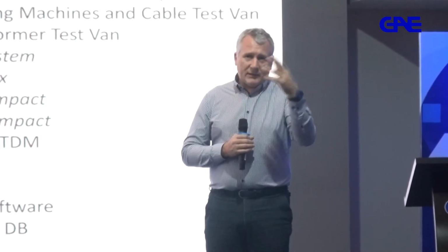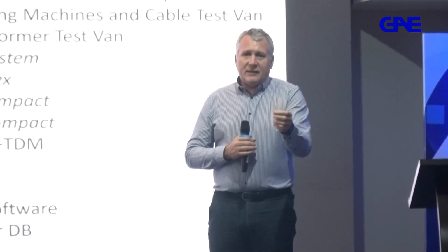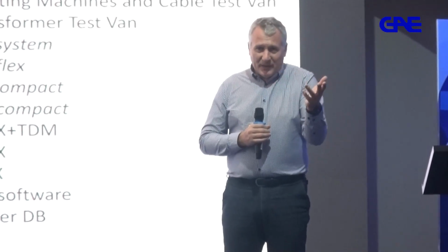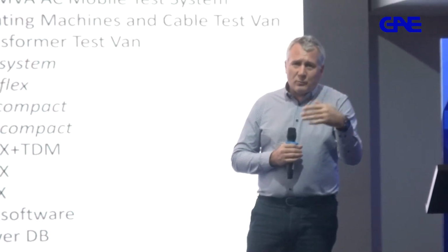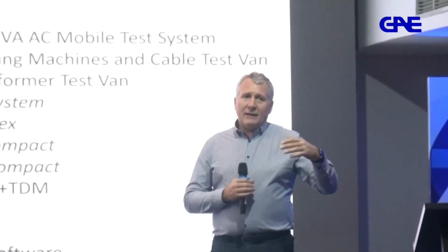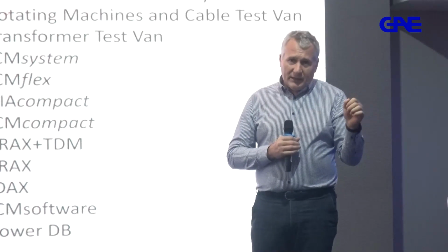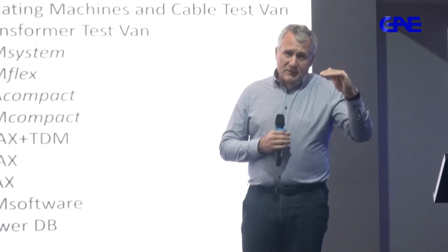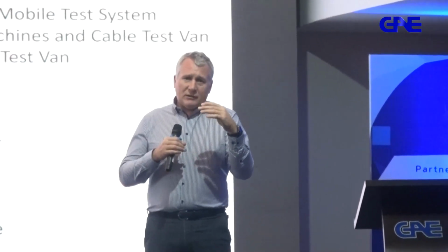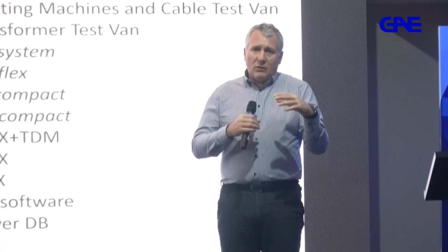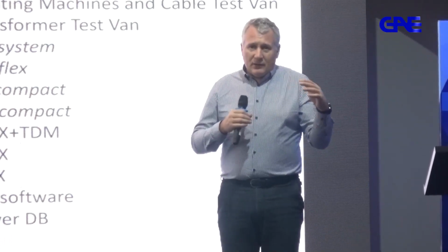It's the same as doing, let's say, radar sweeps. If you have a sea of noise, let's call it electronic noise, you will not see the target because it's covered by noise. So now the question is, how do you suppress that noise? And usually there are either environmental ways to do it, or what I mentioned to you, gating, or raising the noise floor. But if the test object exhibits certain partial discharge issues and they sink in the sea of noise, no person on earth will be able to help you with that.